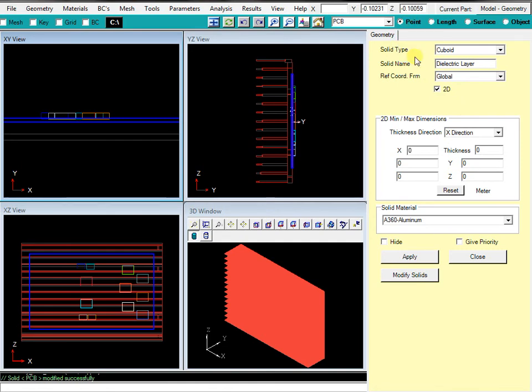So we'll put point key planes, and that's going to be going on the closest key plane. You can see that, and then that'll update in our model where we're looking, and then pick our Y value there, and then there. Oh, okay, sorry. Make sure first that your direction is right, and in this case our direction is going to be in Y, and then come back and click it.